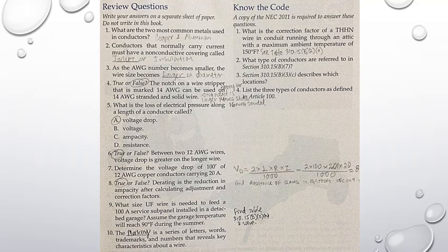You get your factor multiplied by 100. That gives you 91 amps, which, if you go back and look at table 310.15(B)(16) once more, you see that the allowed ampere that falls under 91 amps would be your 95 amps, and it's going to be the number 2 AWG wire. 2 AWG wire could carry amperage from 86 to 95 amps.